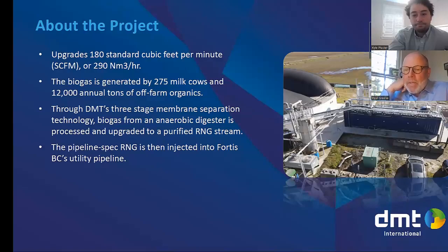So it sounds like membrane systems are fairly elegantly simple. I think the polymer chemistry is where it gets complicated, but from a day-to-day operational perspective, they're pretty simple. Yeah, very easy to operate. How about the compressors? You've got to just change the oil there periodically? Yeah, the big moving part is the compressors, so we emphasize having good service and maintenance. We have partnerships with all our compressor suppliers and local technicians, so if anything does happen, we can get on site within 24 hours and have the compressor up and running again.